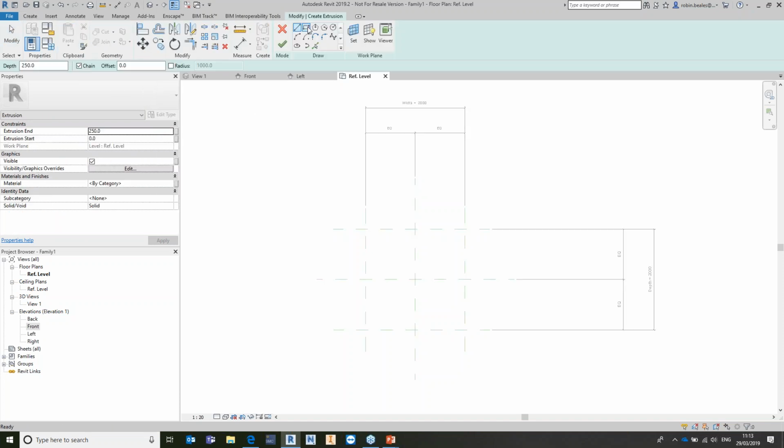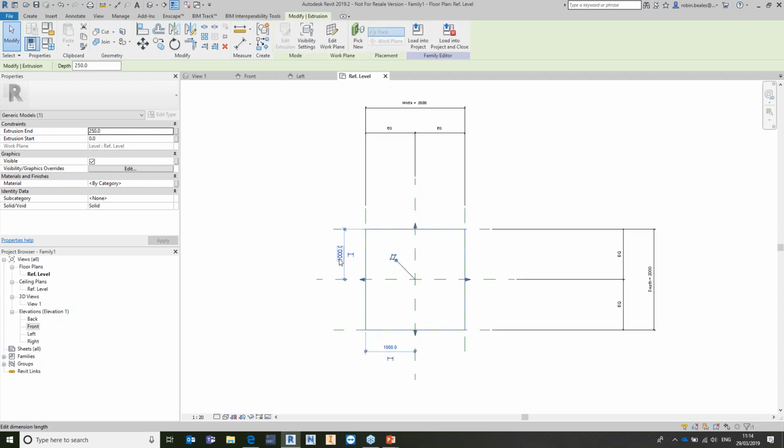I'm going to create an extrusion. I'm going to draw a simple rectangle and then use an align tool to basically lock my geometry to that intelligent skeleton that I've just created. So rather than doing a simple sketch, locking it with constraints in a sketch and then extruding it, I'm creating work planes to drive a lot of intelligence. This is a very simple model, so it looks like overkill, but you can imagine when you've got windows, doors, an entire conservatory running parametrically, this process is going to be really key.